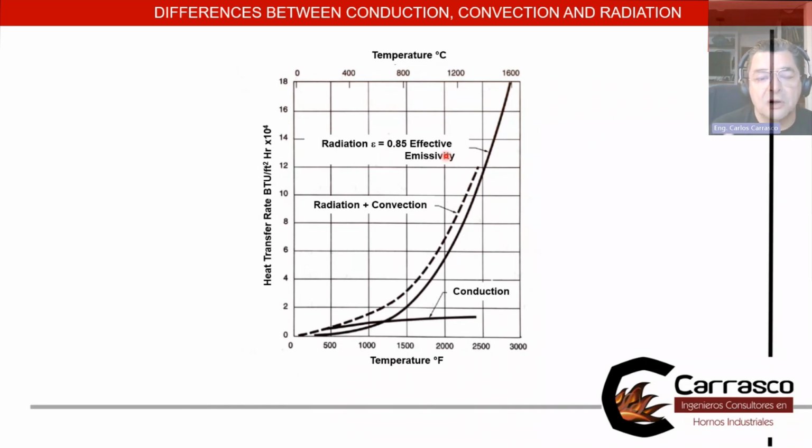also from the doors. So the engineer, when selecting the furnace, when selecting the burners, always has to decide what's the best size of the furnace, how much volume I need inside to accommodate my load, number one. What is the spacing I have to put between loads? Because when it's radiation, as I mentioned before, the radiation is based on the exposed area of the material. The more area I can expose to the heat, the faster the heat treatment is going to be.